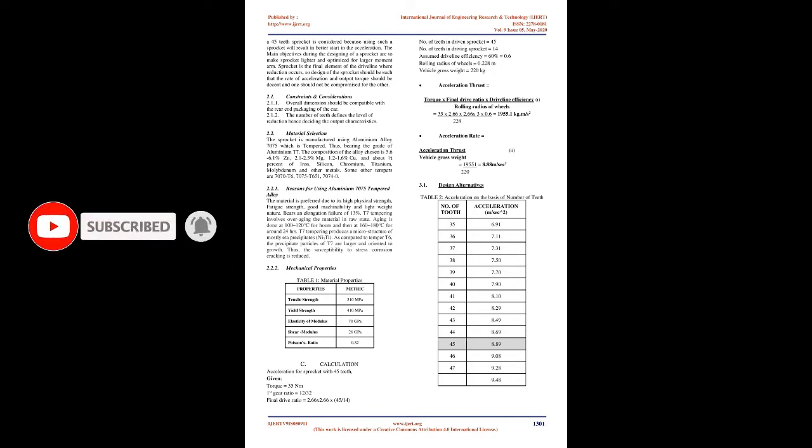2.2 Material selection. 2.2.1 Reasons for using aluminium 7075 tempered alloy. 2.2.2 Mechanical properties. The sprocket mainly interlinks with the differential and the drive chain. The tooth count of the sprocket is the main factor influencing the acceleration of the car and transitions between the gears of the transmission during dynamic events. The sprocket is built to take the linear force of the drive chain and produce rotational energy from it to rotate the differential, which is further connected to the wheels.